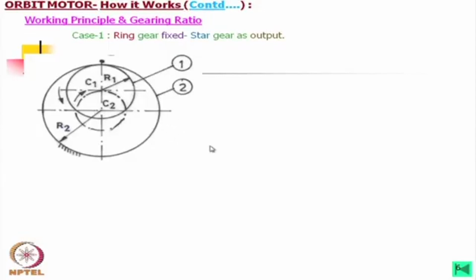What I have mentioned, the teeth here are epitrochoidal teeth, which are from the family of cycloidal teeth, and this motion is called cycloidal motion. In that case, the outer one is the describing circle of the outer member, that is in this case the envelope, ring gear, and the inner one is the describing circle of the inner member, that is the star member.